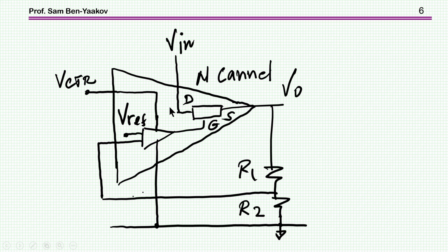One way is to have two inputs, one a power input going to the drain and then to the output, and then a control input which will be higher than the Vin to supply the voltage to the gate, which has to be higher than the source. So by this we can overcome the problem that I've described.